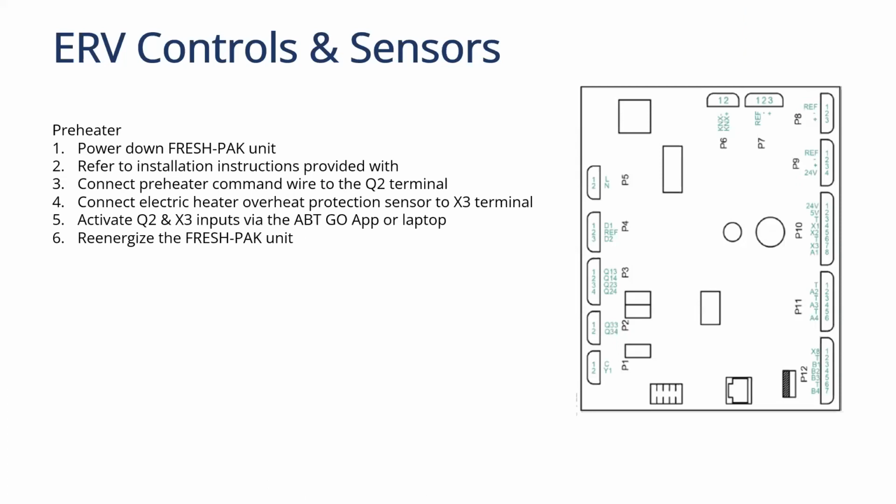Okay, lowest temperature that it can operate. I'll have to get back to you on that one. I don't have that handy here, but I know we do have a defrost control, and we have things in place that if it senses too cold of a temperature, it will redirect the air and defrost the core of the ERV separate from the heat pump and the defrost cycle. On a heat pump, it has its own defrost cycle, and the ERV has its own, but I will follow up and get that answer back for you for sure.